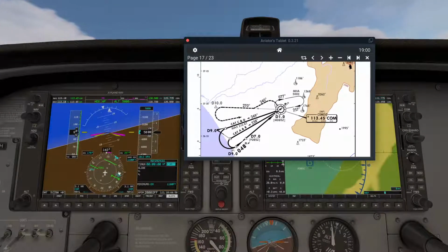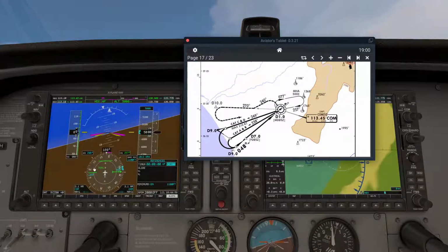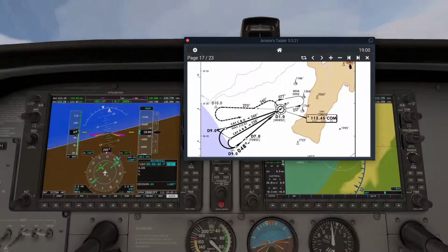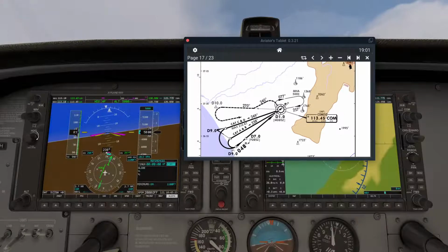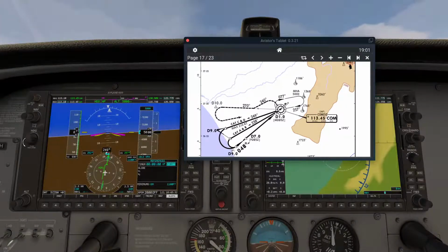Also, we can home direct to the VOR, but it's better to intercept at this stage, because if you intercept the course 257 inbound to the VOR, for the rest of the holding procedure after the entry procedure, you can follow the procedure and intercept the course 257 again after completion of the entry, easier than when you fly direct to the fix.